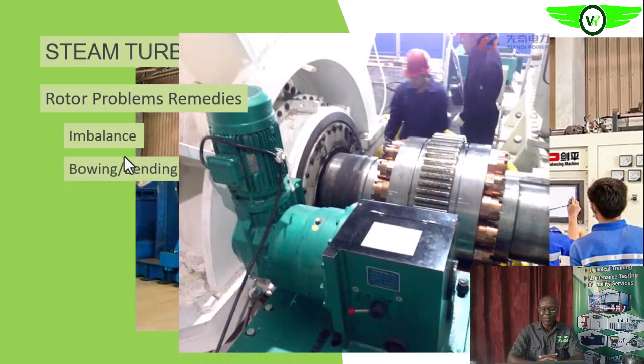Then for bowing or bending, remember bowing and bending too will also show up in one-time RPM, but we don't need to allow the shaft to bend or bow during normal operations.